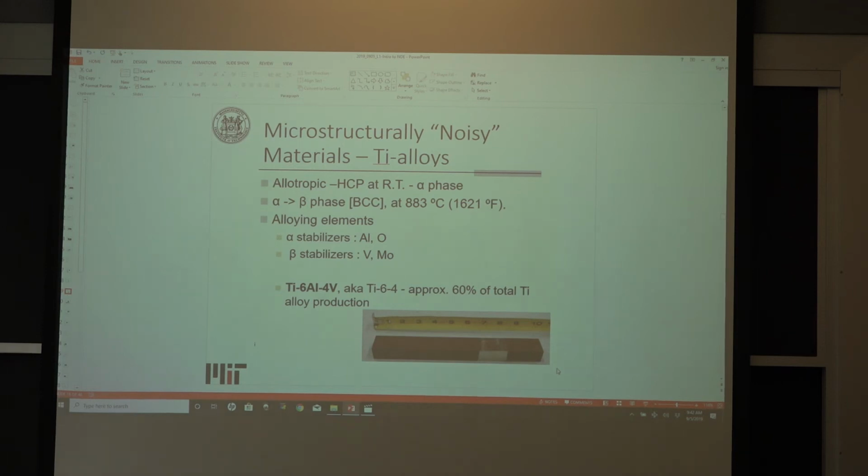If you have to perform a surface preparation activity before you do the inspection, it's relevant. So if you did an inspection through the case layer, you're not going to get the same output as if you perform the inspection and you removed a layer of material.